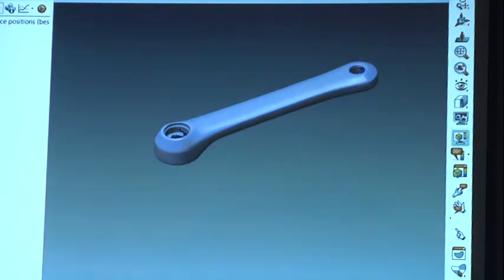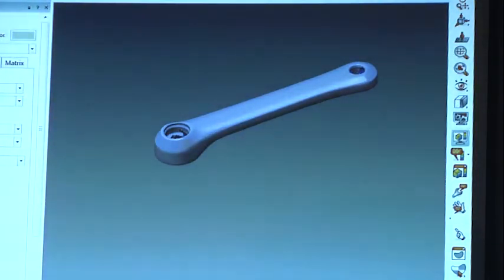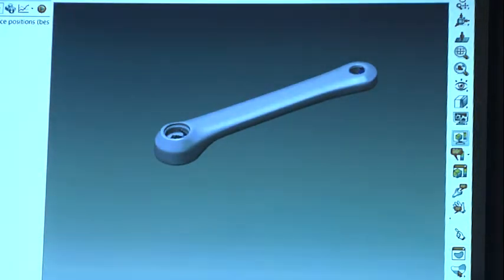And if I pay attention in the tree view, I now have my mesh, which is the unified model. But I also have a group that is now hidden by default, where I have my 2 original source objects. So those ones are kept in there in order to update everything. And if I look in their properties, they are now considered as source data objects. So they are not used for computation. So if you do a best fit, they are not used. If you do a color map, they are not used. They are not used for any computation except to create that mesh. And that's the one you will now inspect and analyze.